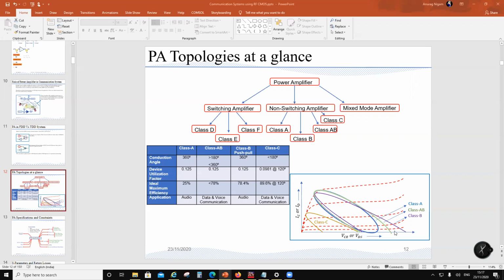Now, if you hit it with power, then the self-biasing will cause this loop to balloon out into a rectangle. So you can plot that also and see. But to a certain extent, you will still see this kind of curves under output characteristics. So this is what happens with the linear amplifier.